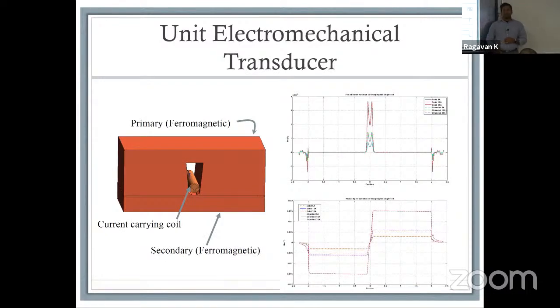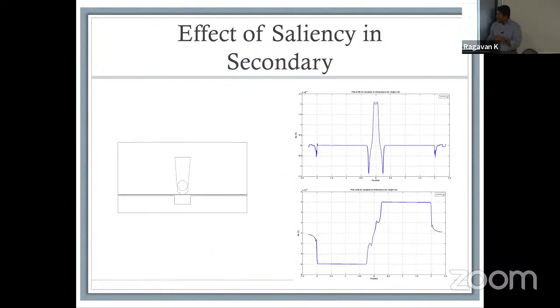So, if you're talking about the idea of basis functions, the first thing you would remember is that I said each current applied to the system gives you a certain amount of field. What that means is, the first question you would perhaps want to ask is how that looks with changes in geometry. The first thing we did was several simulations specifically to analyze the impact of the slot geometry, the coil placement, and the rotor on the back itself.